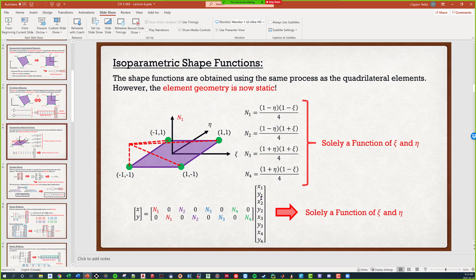Where the approximation comes in doesn't really play a role in the shape functions. Where the approximations come in is what we discussed in the previous lecture, when we said it's all approximations, because we're multiplying by those nodal displacements. Those nodal displacements are the part that starts to switch things up and creates the approximation. It's not so much the shape functions, if that makes sense.